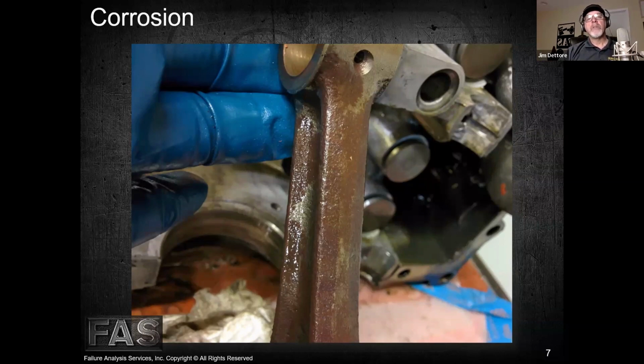And the problem is that not only is it unsightly, like the rust and corrosion that you see here, it can generate secondary debris in the form of iron oxides, which is rust, as well as potentially producing pits that can be stress concentrators or stress raisers that could lead to fracture later.